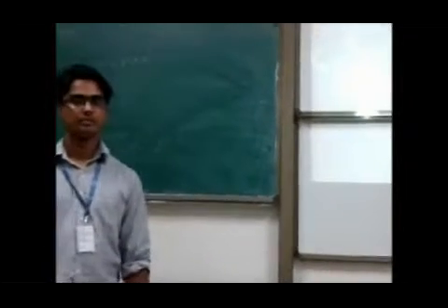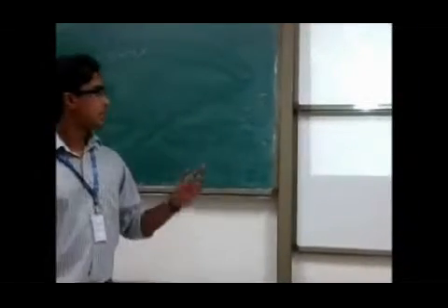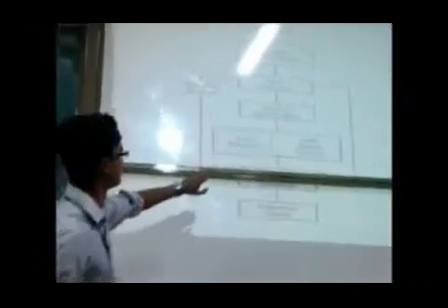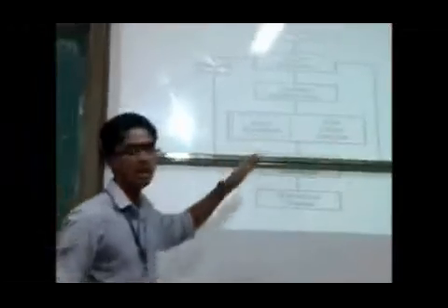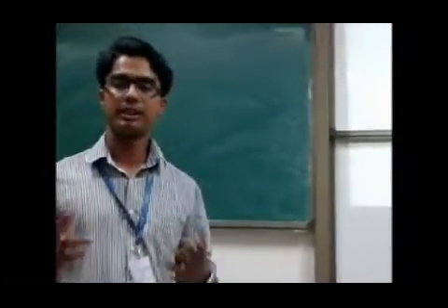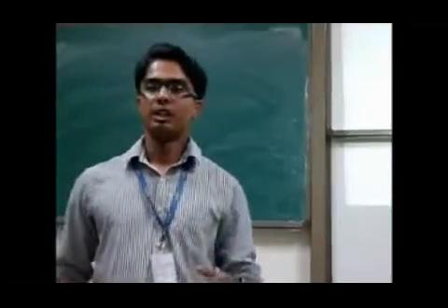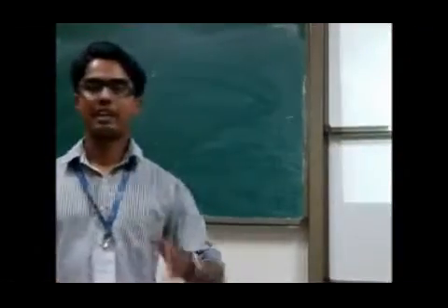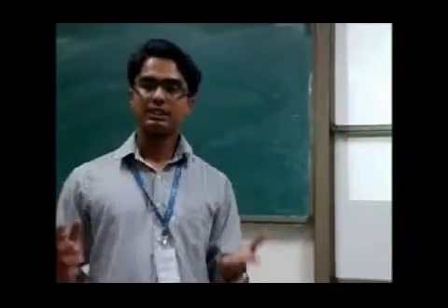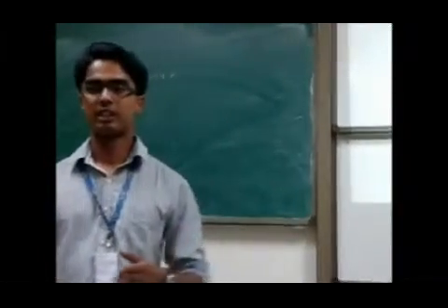This is a general sensor based on the Hall effect. In this diagram, this is actually the Hall element. The Hall element is constructed from a thin sheet of conductive material, with output connections perpendicular to the direction of current flow. So whenever it is subjected to a magnetic field, it responds with an output voltage proportional to the strength of the magnet.